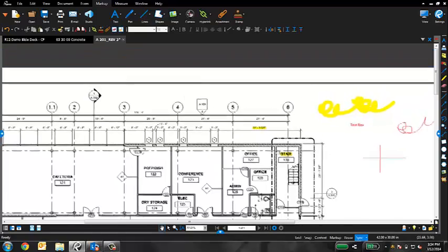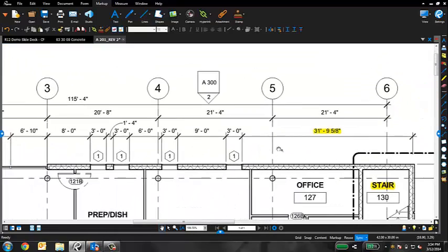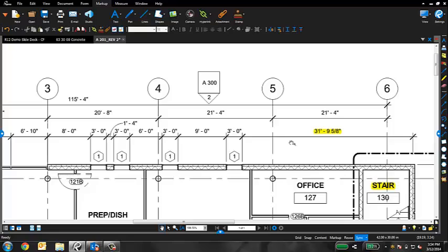Now, a real world scenario of utilizing markups is looking at a mullion spec. So let's do that. I'm going to go ahead and click my C hotkey for cloud, and I'm going to click Q for callout, and I'm going to say revise mullion spec. Now, historically, this particular markup would either link to another page with the mullion spec there, or the mullion spec would be in a completely different document, or maybe it wouldn't even be associated at all. Maybe it would be just up to the subcontractor to find that information themselves.